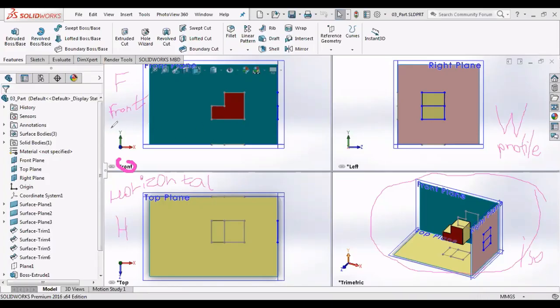You have to draw the front view, the horizontal view, and the profile view, using sizes. You have to measure using a ruler and draw with pencil. The note is the edge: edges should be correctly projected, so this point should be projected and lie in one line.